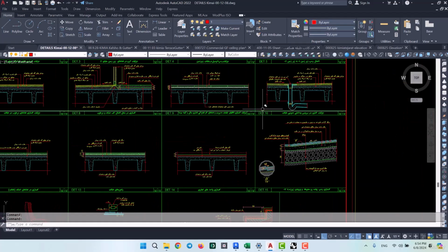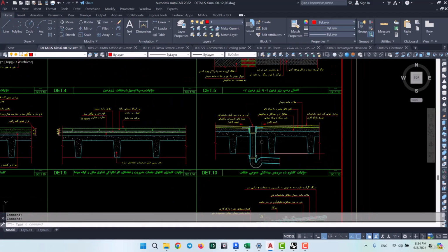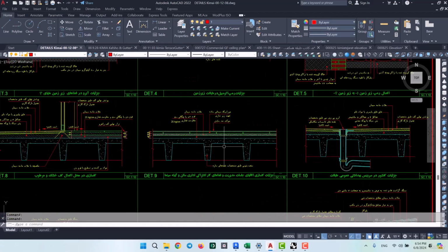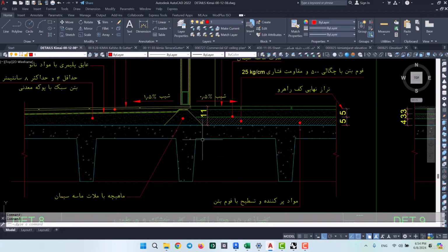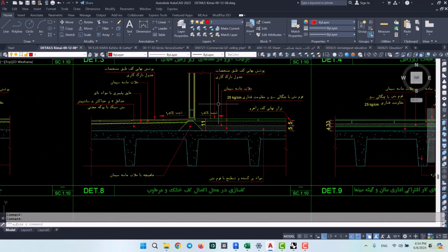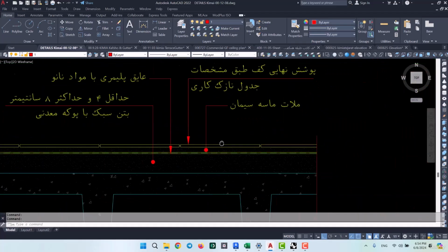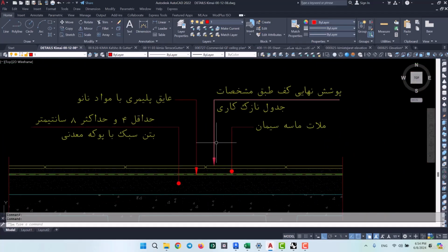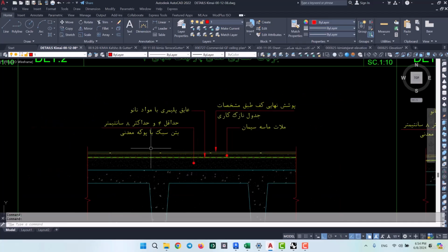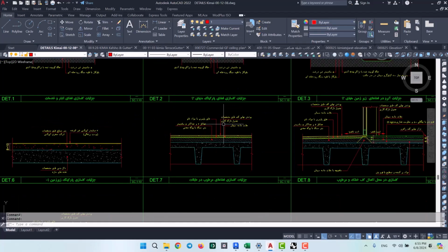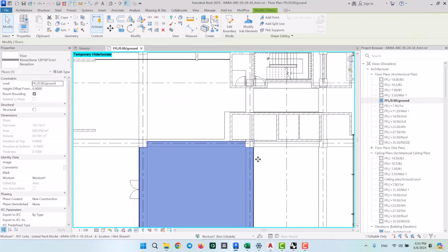Now, for example, here we have some floor drain details, or the flooring of the management offices. And then here we have an area that is dry and wet, where we have the connection between the wet and the dry area. So these details need to be considered in the types. And for example, the flooring of the wet areas goes like this. Final coverage based on the table, then we have the sandstone mortar, we need some insulation, and then light concrete with mineral pumice. So you could also make lots of use of this detail for the flooring of your levels.